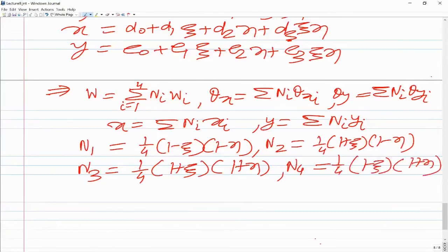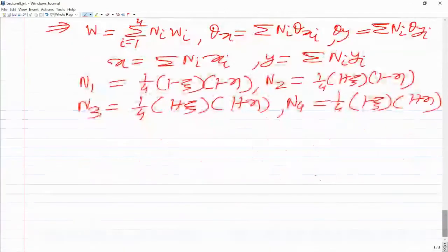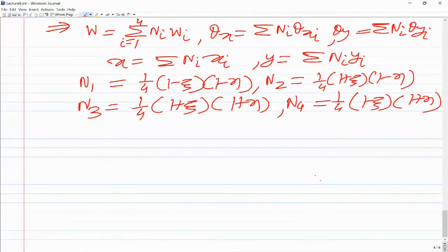So now if you remember, I have also introduced the concept of Jacobian matrix while discussing the plane stress, plane strain elements. So we had said because for defining the curvature tensor and the shear strain tensor, we need the derivatives of shape functions with respect to x and y. The shape functions are explicitly written in terms of xi and eta, so we can get their derivatives directly with respect to xi and eta, and then we have to write the derivatives of this shape function with respect to x and y. So we use the concept of Jacobian matrix.